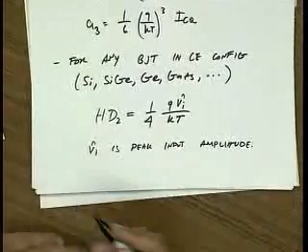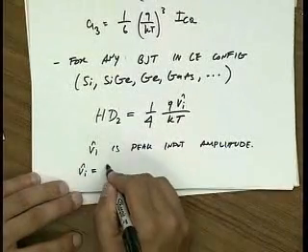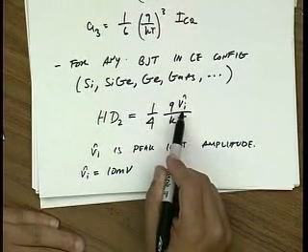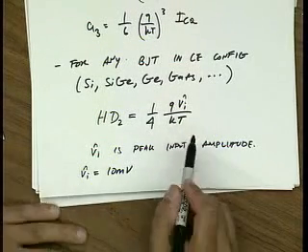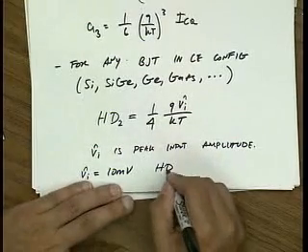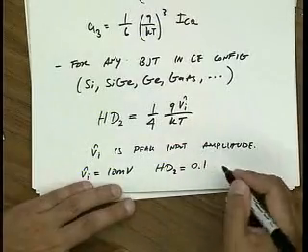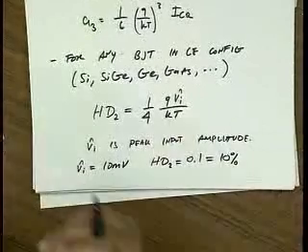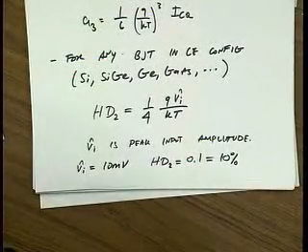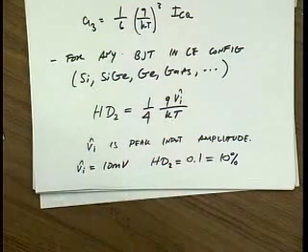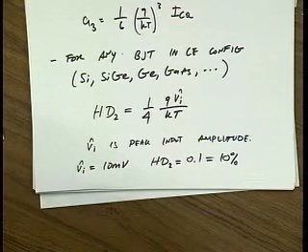All right. So let's say that the input amplitude is 10 millivolts. KT over Q is roughly 25 millivolts, and take 1/4 of that, I get that HD2 is 0.1, or about 10%. Okay. That's actually pretty shocking, right? Because 10 millivolts is a pretty small voltage. So I put 10 millivolts into this amplifier, and the output has 10% second order distortion. Right? You could hear that.